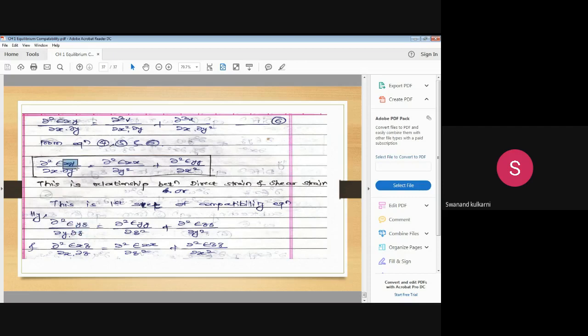Whenever this relation was along xy, we considered the two-times differentiation of εxx and the two-times differentiation of εyy. This particular equation represents that whenever the shear component is differentiated with respect to x and y, εxx, that is strain along the x-axis, was differentiated by y, and strain along the y direction was differentiated with respect to x, two times. Is it okay?